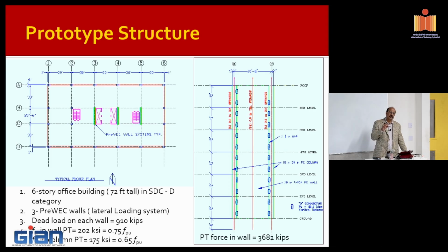So you have given, so this is in a high seismic region. So let's focus on the walls. We chose to put in, or at least the designer selected 3 walls. And if you calculate as per the current design code, the amount of damping that is required, which I think is 18%, means that you have to add some damping to the system, right? Because if you just have only the wall, that won't have this 18% that they're looking for.